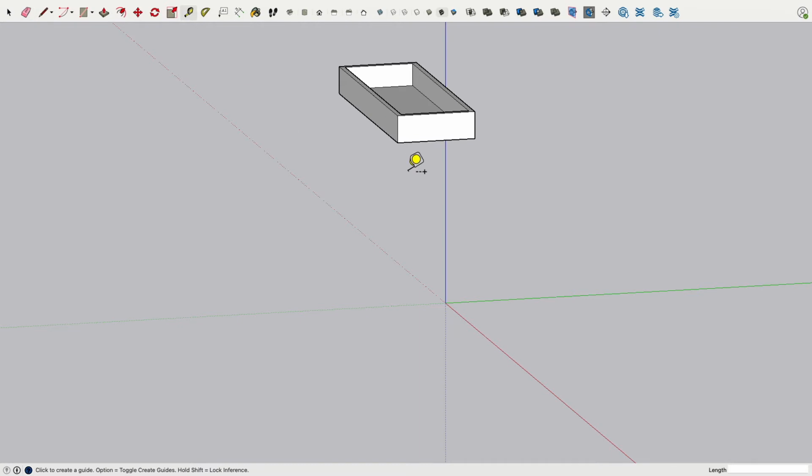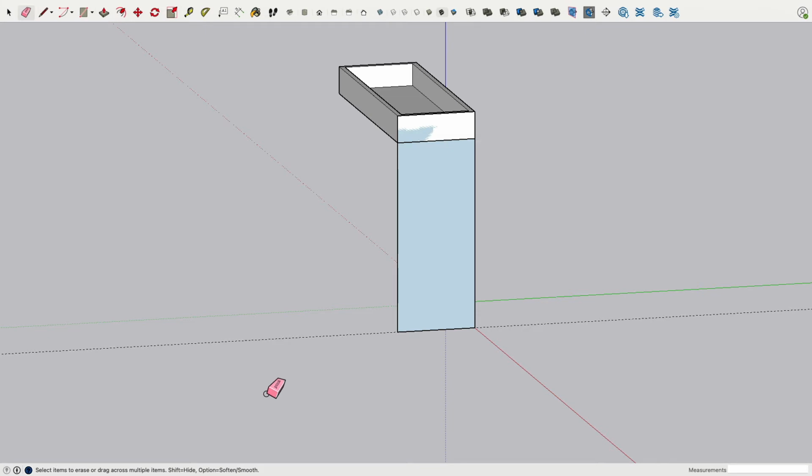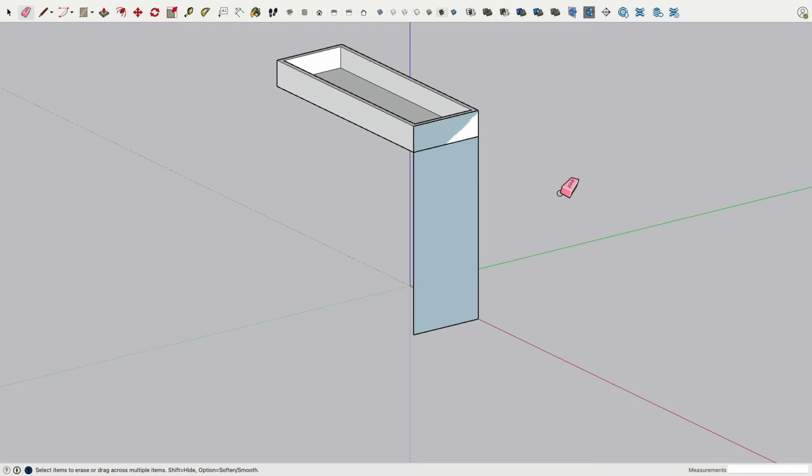Let's do this one more time. Click and drag, press the up arrow key, go to there, there it selects it. Cool. Okay. Now, you can go to the rectangle, and then from here, go to there, move the mouse down till it snaps actually on that guideline. Pretty good. Now this guideline we can delete. There. Perfect. Okay. Snapping in SketchUp works actually really good, but like you saw, not always. And then it's good to know when there are ways how we can fix this.